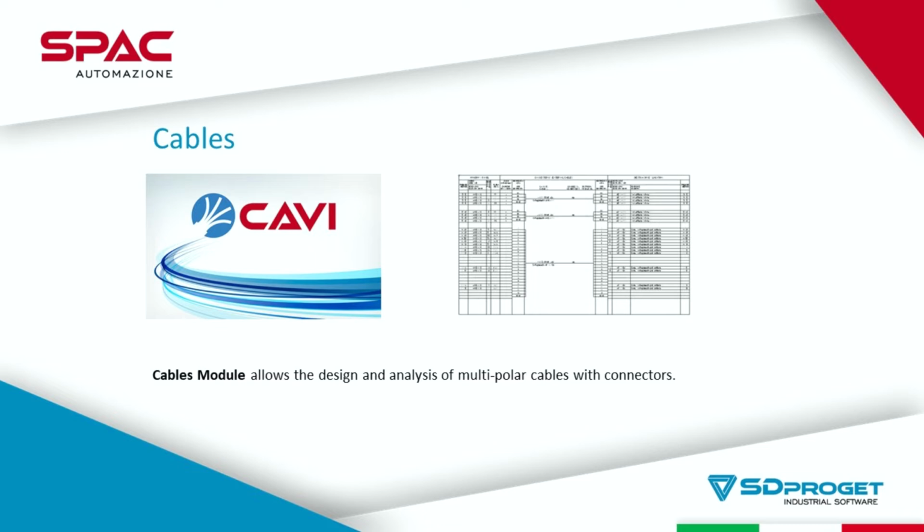So you will see all the input pins at one extreme of the cable, and all the output pins with the specified connection element or line on the other side of the drawing. This is useful when you need a detailed representation of the cable, or in case you need to connect 2 different elements in 2 different electrical panels without going through any terminal block.